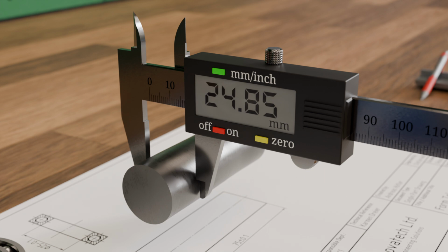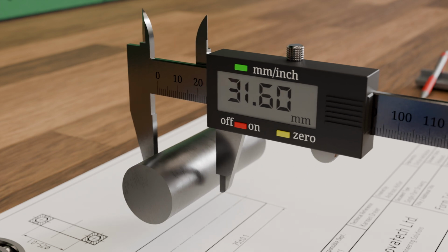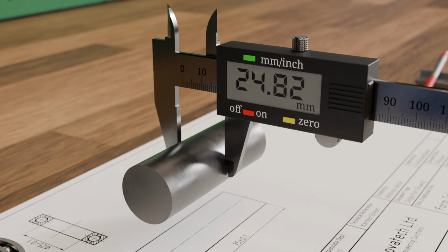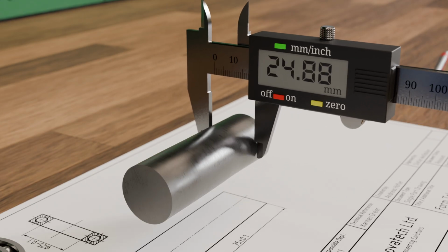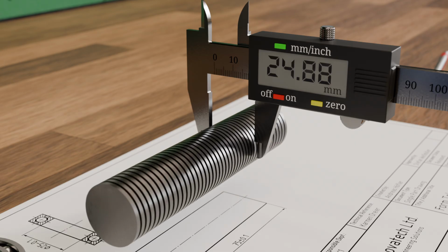If the diameter of the shaft were measured at different points, it would still lie within the dimensional tolerance despite the curved form. The dimensional tolerance could, in principle, be chosen as small as desired, but it could not prevent the shaft from being overall curved. For this purpose, the shaft can be imagined as being cut into many small discs, each of which lies within even the smallest dimensional tolerance.